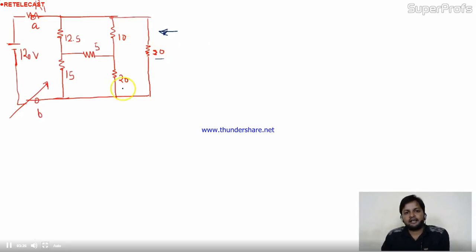No. Are they connected in parallel combination? No. Though the starting point is the same for these two resistances, the ending points are different. And for the parallel connection definition, the starting points and ending points should be the same for elements connected in parallel. The same thing is with 20 and 30 also. No series, no parallel, nothing.